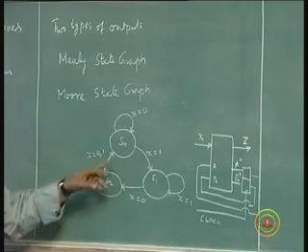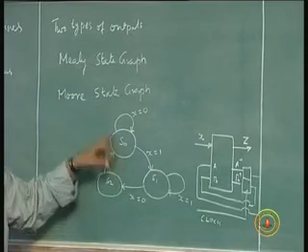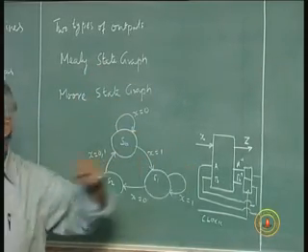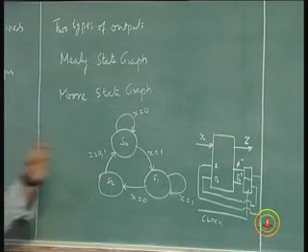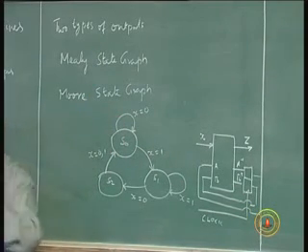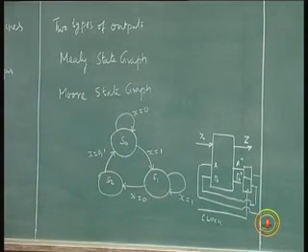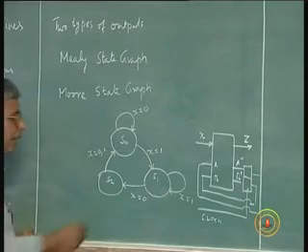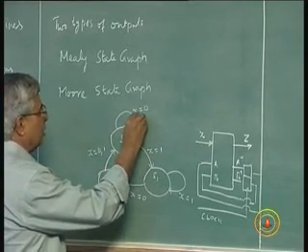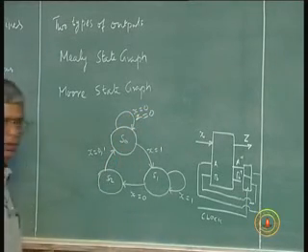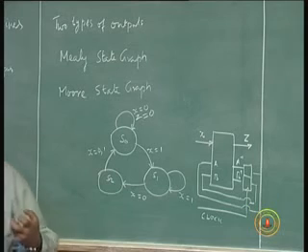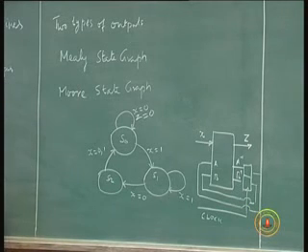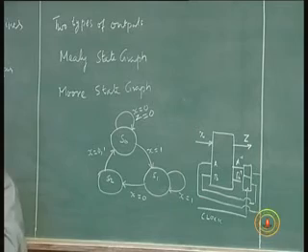For example, if this is a Mealy graph, and this machine is a Mealy machine, then for each arrow of the input, I should also define an output. So I can say the output is 0. The circuit may be in state S0. When the input X is 0, the circuit remains in state S0, output is 0.